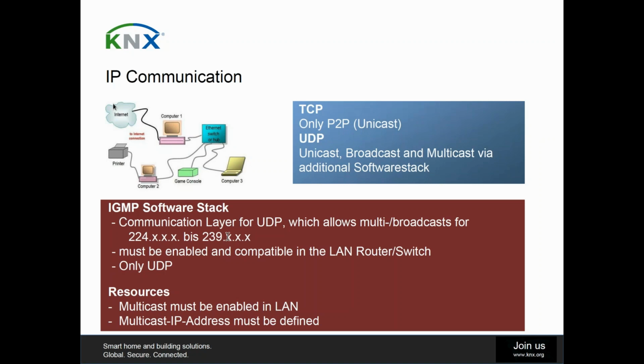So the normal multicast address you will know from KNX here is just a standard multicast, but of course you can, at least theoretically, choose different ones and make groups of multicast islands, for example, if you have a lot of different infrastructure in a bigger project.